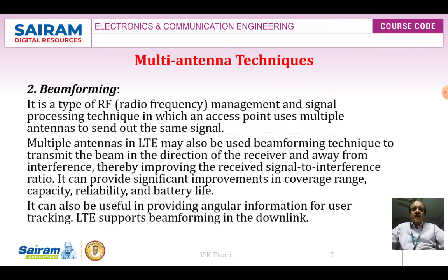Another multi-antenna technique is beamforming. It is a type of radio frequency management and signal processing technique in which an access point uses multiple antennas to send out the same signal. Here, multiple antennas in LTE may also use the beamforming technique to transmit the beam in the direction of the receiver.